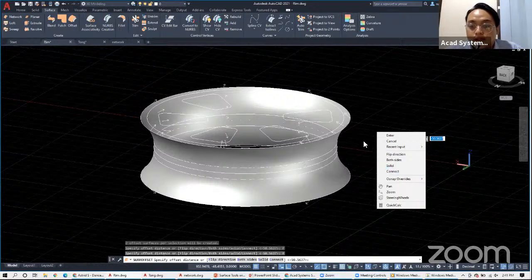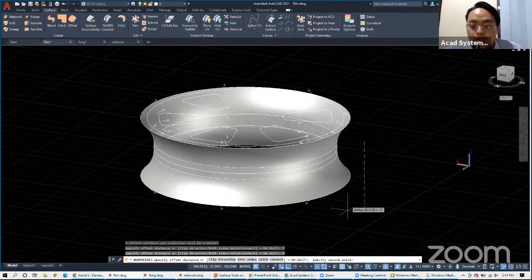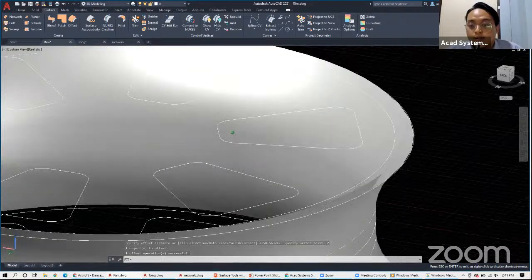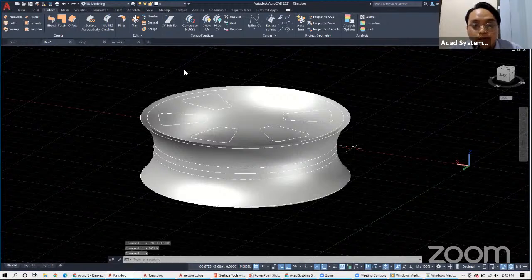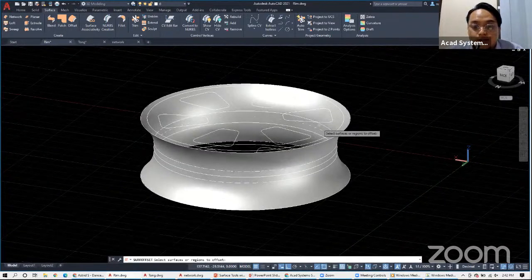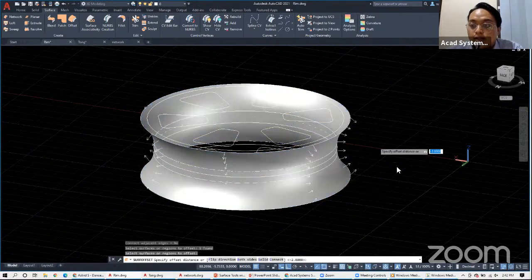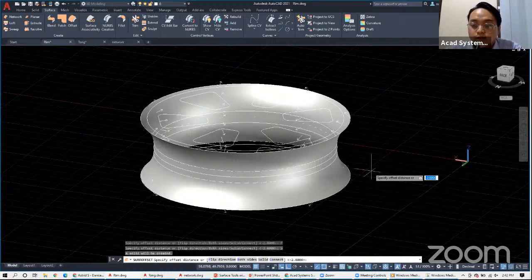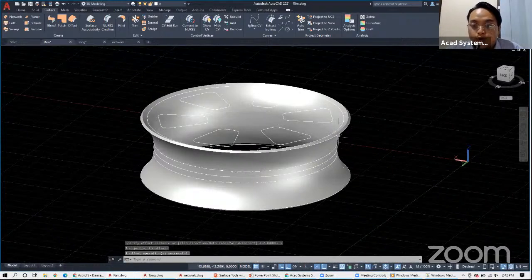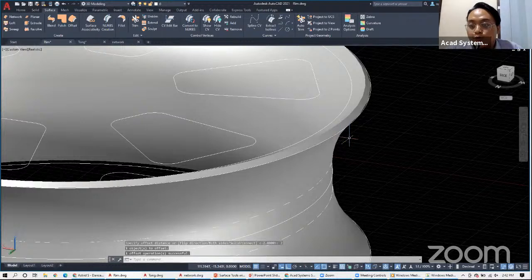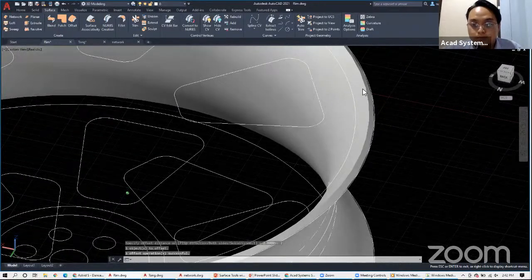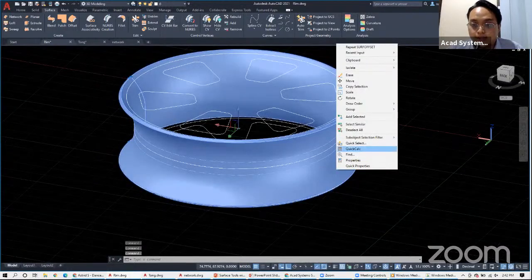Okay, let's say if I'm not using a solid, I just specify the second point, S2. You can see that it creates another surface, but the surface is hollow. And that's not what I want. What I want is to create an offset by clicking this outer part, changing the direction, and I just click on solid. So it will create a solid, and the offset distance is 2. You can see that this one is no longer hollow. You can either use thicken or offset. And for now, I will just hide this.